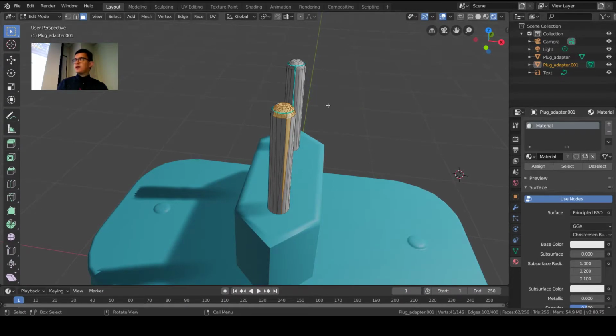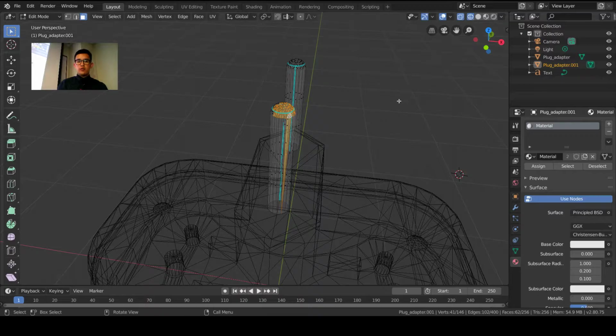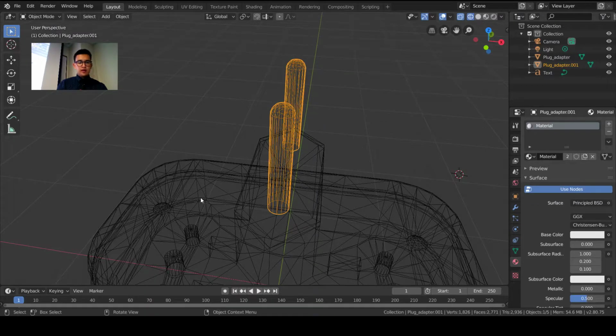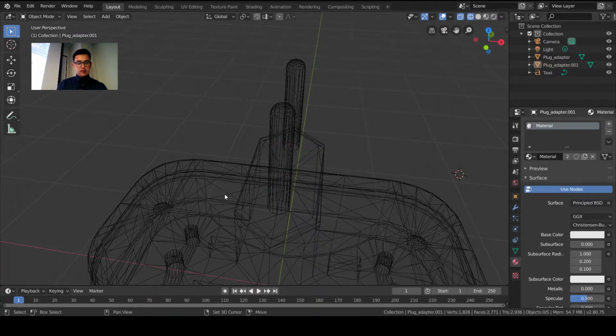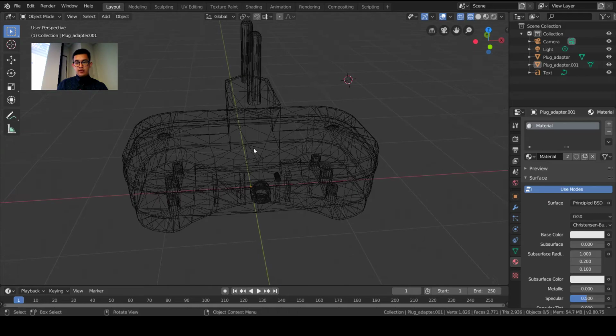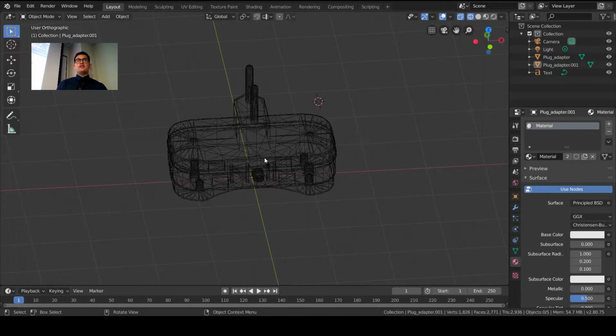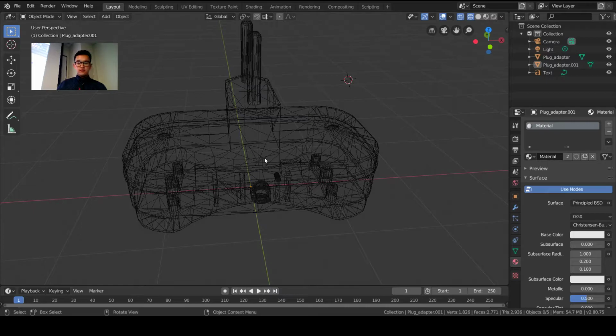Go to Blender. Okay. In the top right here, I can switch to a wireframe mode so you can kind of see the perspective better. And let's go back to object mode. So here's all my polygons. So if I press 5 right now on the numpad, here's the kind of orthographic mode versus perspective mode.